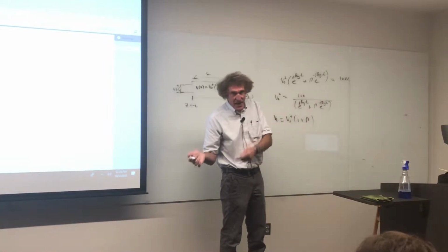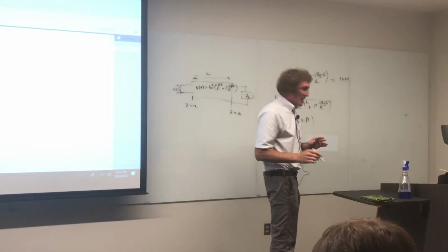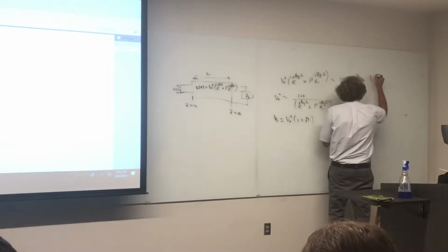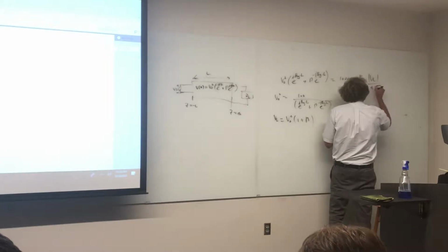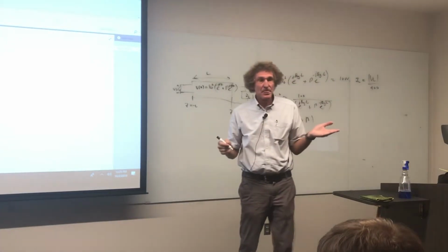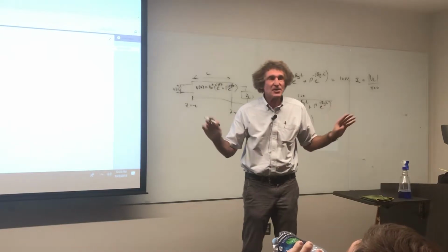Now, after that, the load is 400 ohms. It's pure real, right? After that, to get IL, the only thing I do is take VL magnitude over 400. And now I've got IL. Follow me on this? Now, the load was strictly real, right? There's no imaginary part.